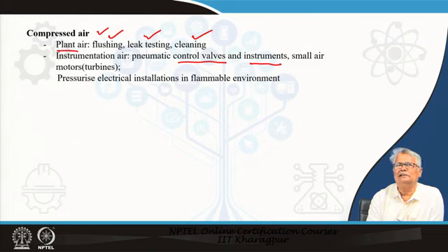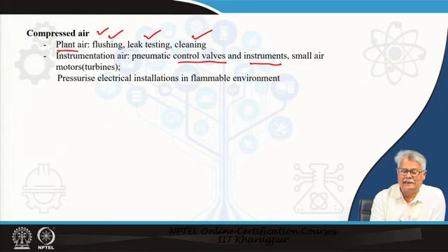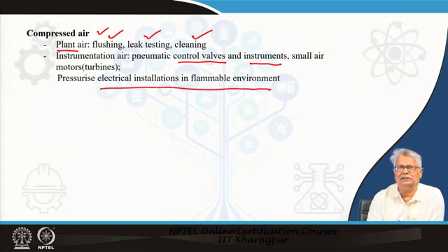Small air motors like turbines are also used for certain handheld instruments at times, or sometimes even for installed equipment. Like in furnaces, you have soot blowers driven by air motors or air turbines, whatever you may call it. You have an arrangement of making electrical installations in a flammable environment safer by enclosing them and pressurizing with a small supply of instrumentation air.